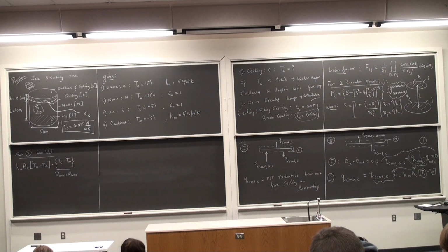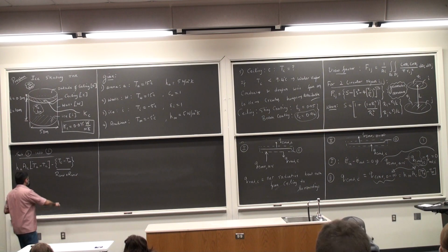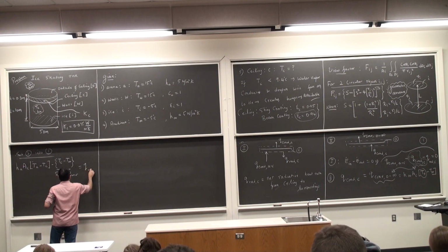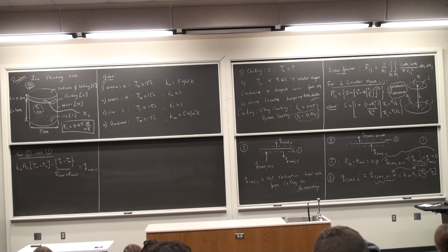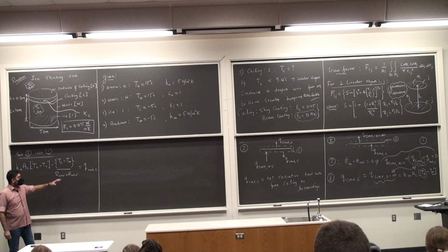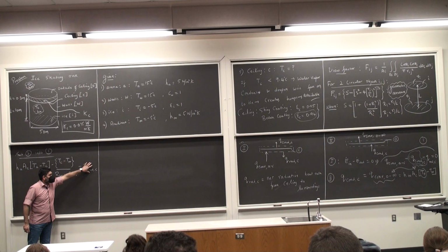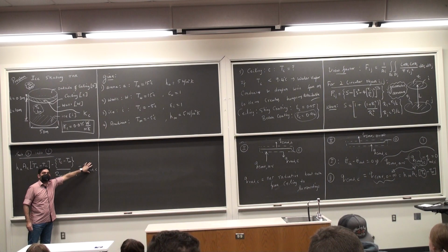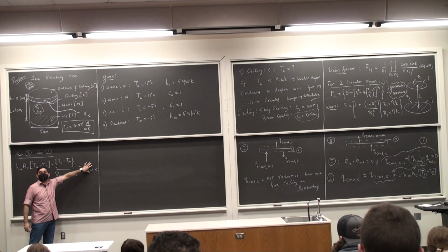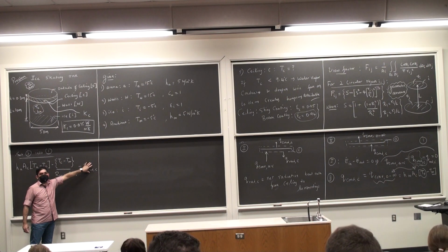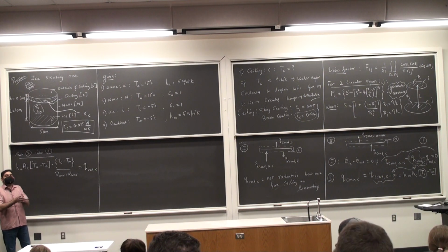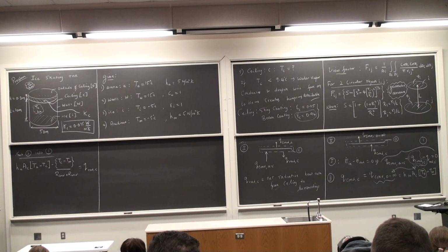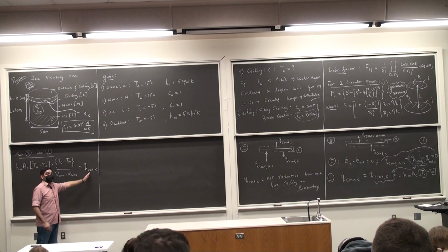Minus Q radiation C, I'm just going to bring it onto the right hand side and say this is equal to Q radiation C. And why am I doing it? Because this is the term that we know how to treat using the resistive networks in thermal radiation. By drawing those 3 branches and then drawing it in the form of a triangle and then having these fundamental nodes Eb, T1, T2, T3, I can actually have an idea of what this is.